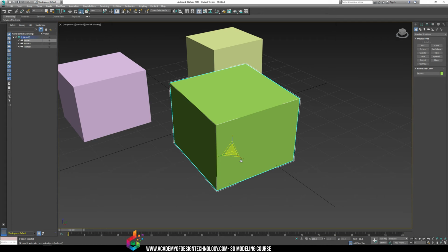By pushing the R key, you're going to notice that instead of having an orb, instead of having these lines here, we actually have a triangle. Now the R key has multiple modes as well. If I keep clicking the R key, we're out of scale mode, and now we're on select and non-uniform scale. We're now on select and squash mode. And if I push R key here, we're on select and uniform scale. For this tutorial, we're going to want select and uniform scale, as this allows us to scale up something very accurately in one direction.